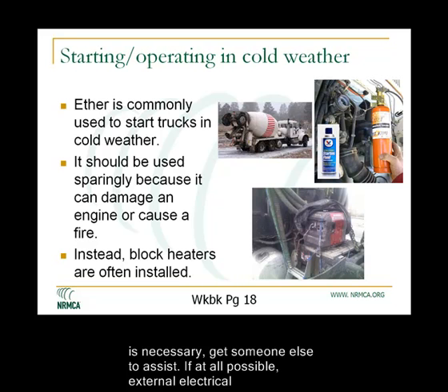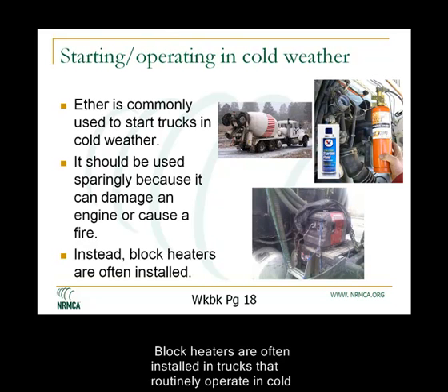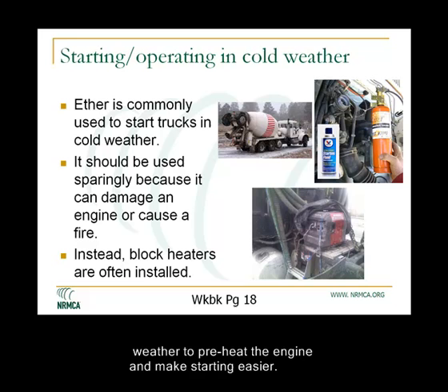If at all possible, external electrical connections from an AC cold start jump cart saves wear on the engine and battery. Block heaters are often installed in trucks that routinely operate in cold weather to preheat the engine and make starting easier.